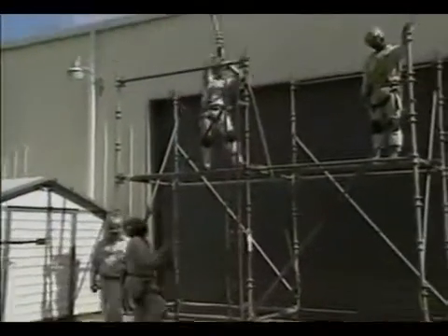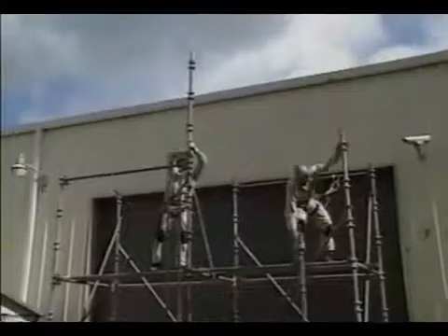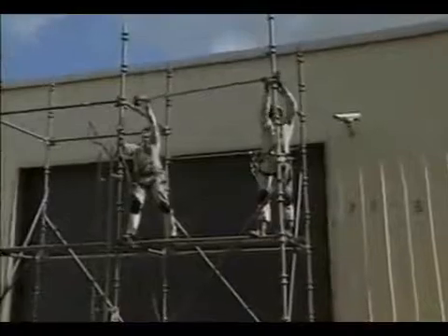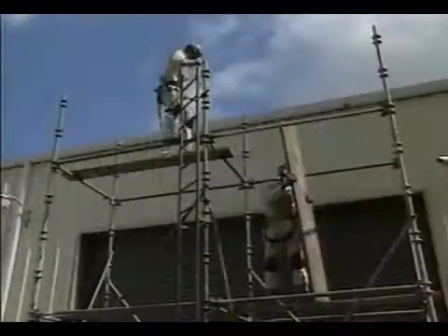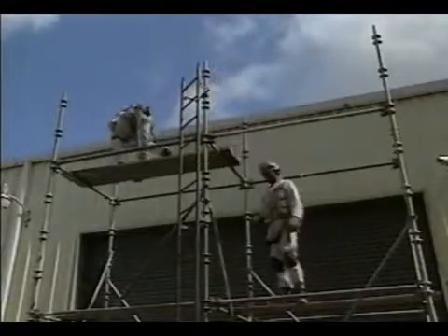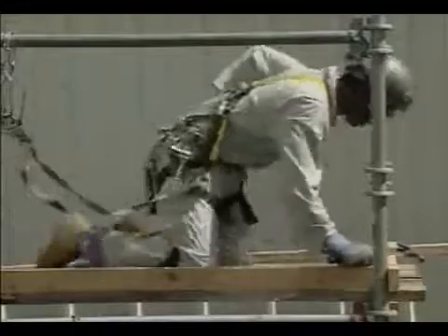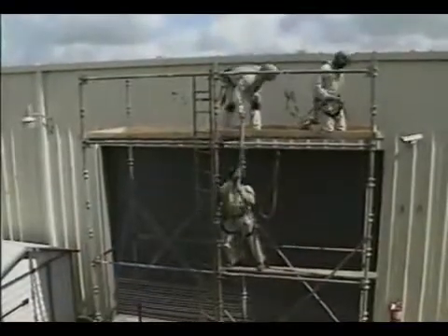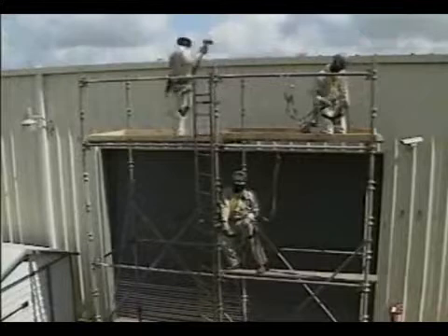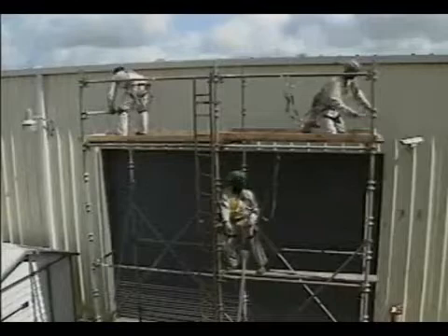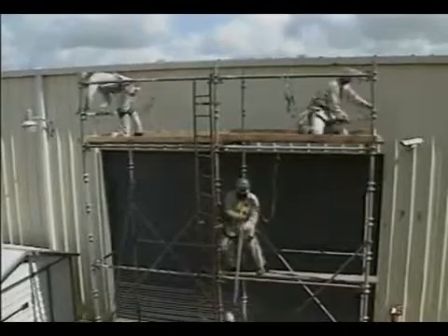Continuing with the assembly, the builders add the remaining vertical legs to the scaffold. Then they install the horizontal members that will serve as the supports for the scaffold floor. After the final section of ladder is attached, planks are added to form the scaffold floor. Once the floor is in place, 2x4 toe boards are attached on all four sides of the scaffold. Then horizontal members are attached to the vertical legs above the scaffold floor to serve as guardrails. One member acts as an upper guardrail, and the other one acts as a middle guardrail.